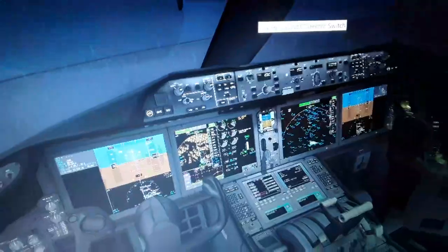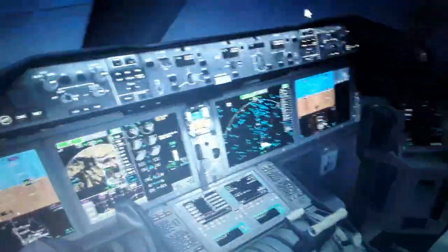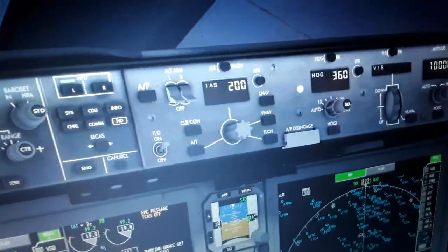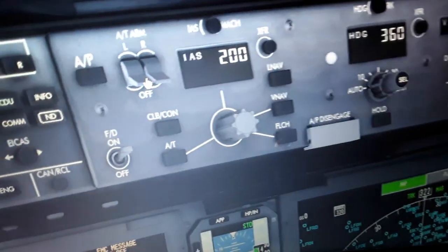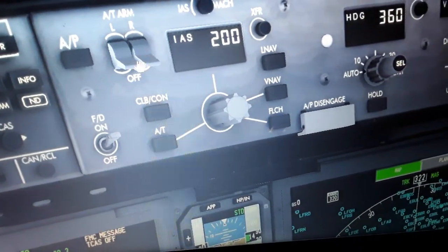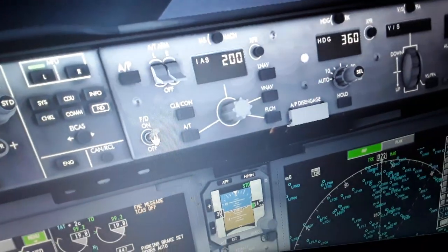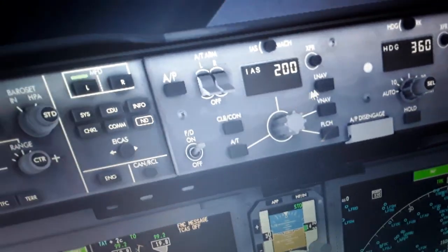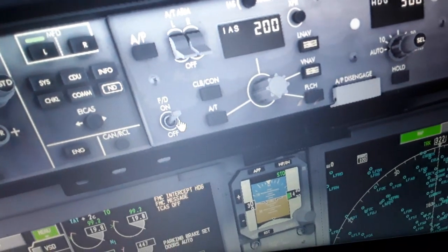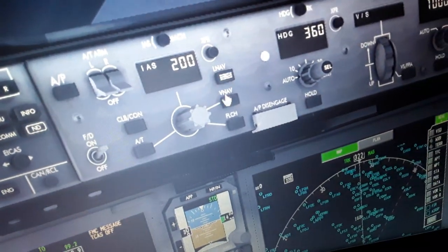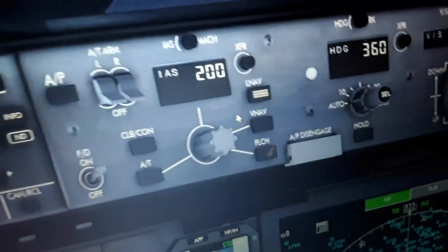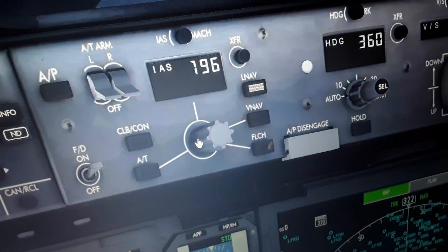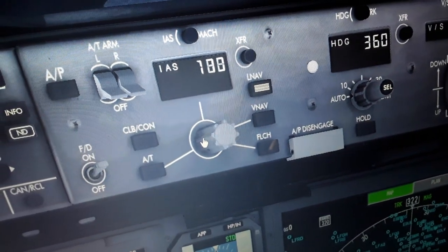So we're going to set the autopilot flight director system panel now. We need it for this flight also, so we have the airspeed selected, autopilot engage, disengage over here. As you can see, auto throttle left and right, engage, disengage, flight director here, LNAV and VNAV, select, deselect, turning off the flight director, deselect the commanded modes. We can have only the flight director on, we can turn them on. The airspeed we can set over here as we wish.